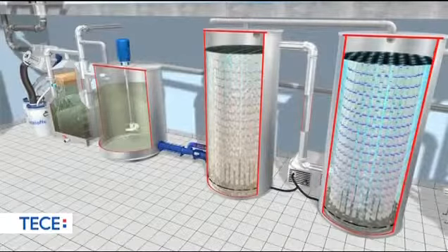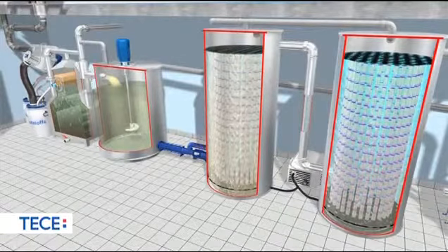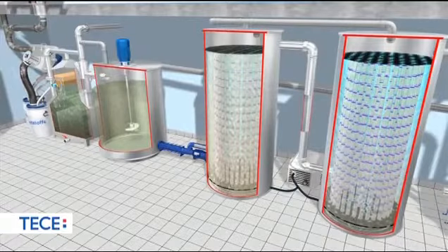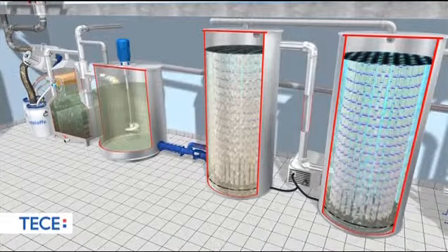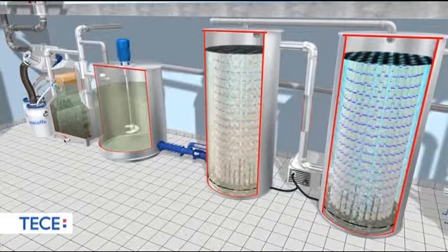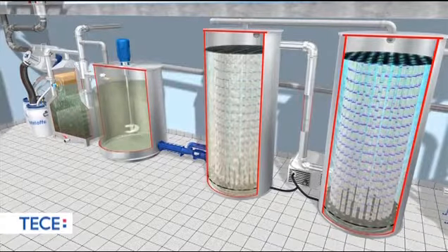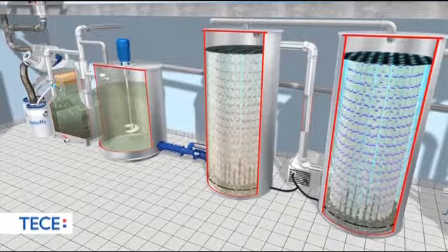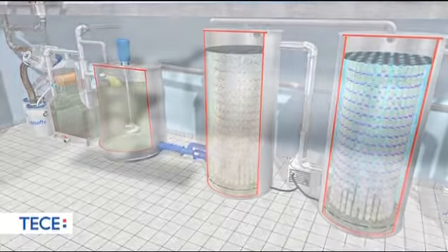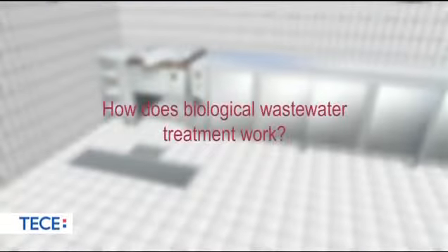These are unable to be separated from wastewater by grease separators employing purely physical processes. Split-o-mat FAT is an additional biological wastewater treatment system that utilizes the self-regulating capabilities of microorganisms in order to break down emulsions and in this way keep wastewater within legal limits.